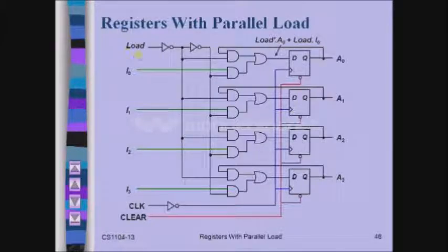Whenever this load input is 1, the new data will be loaded into the flip-flops. If this load input is 0, then these flip-flops are going to retain the previous state. Let us see that with an example. Assuming that initially these flip-flops are holding 1 1 0 0.